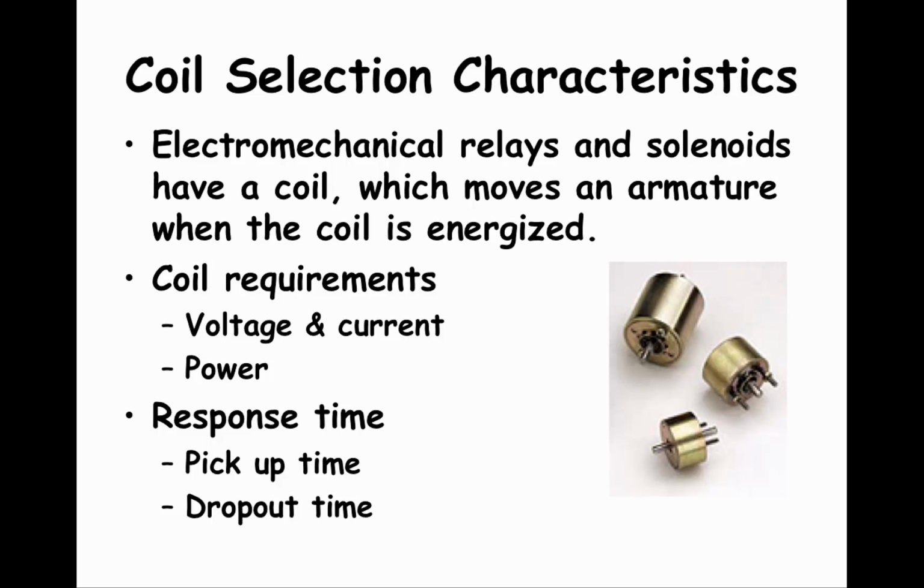So pickup time describes the delay when engaging an electromechanical relay, and dropout time describes the delay when disengaging the relay. In many situations, the delay is not important, but in some situations, things are timed very carefully, so an excessive delay in pickup time or dropout time could be an issue.